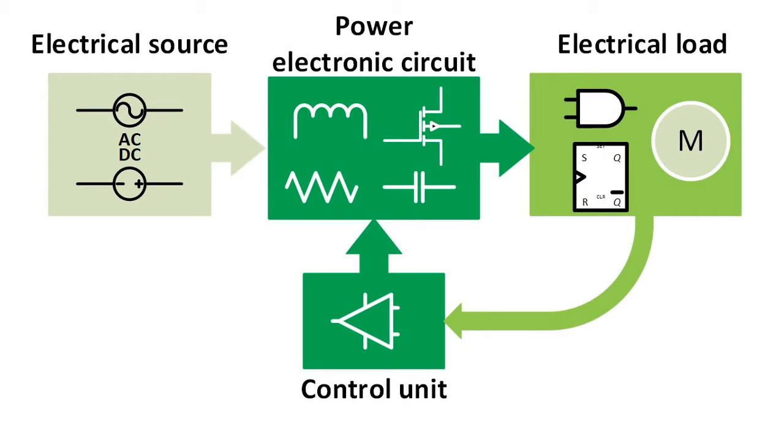Household mechanical switches perform maybe even more than 100,000 switches in 1 decade of use. Unfortunately, mechanical switches do not fit all practical needs. Electronic switches that are part of the power supply circuit switch even more than 100,000 times in 1 second. Even the best mechanical switches will not withstand more than 1,000,000 cycles. Due to this, we use semiconductor switches of selected powers in converters.